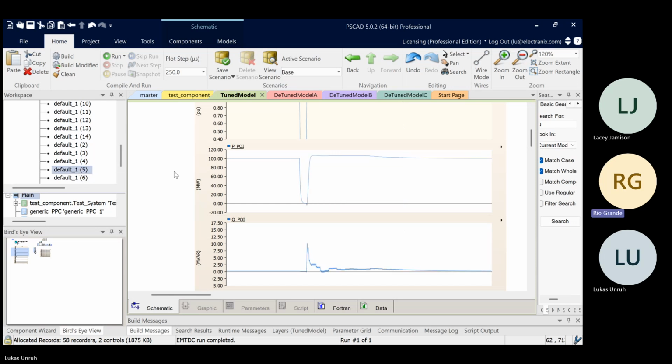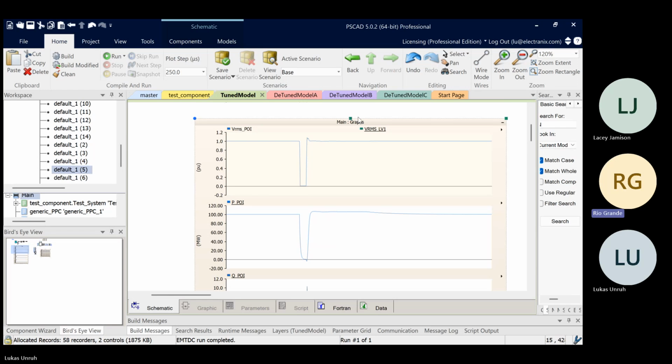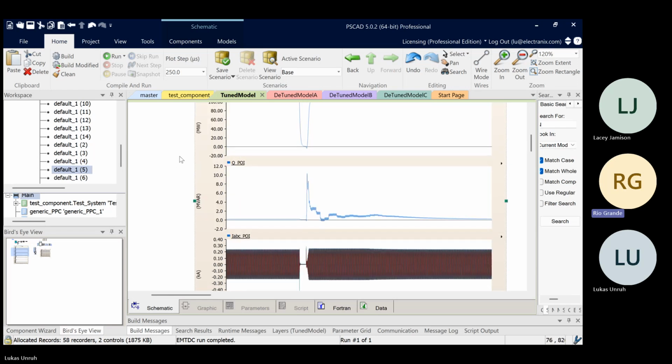And test 5 is just a bolted 3-phase fault for 160 milliseconds, so no problem there in this case. You can see some somewhat interesting reactive power outputs out of the plant after the test here. The reactive power is sort of stepping up and stepping down, and definitely has some movements here. In this model, I would imagine it's maybe winding up a bit during the fault. Maybe the plant controller is winding up a bit, or something like that.